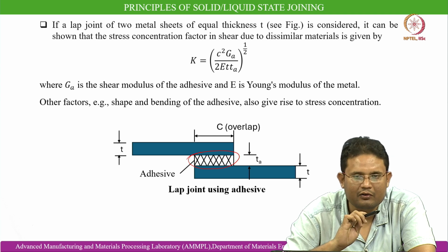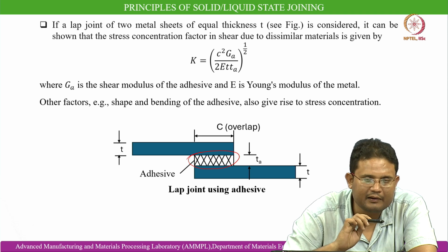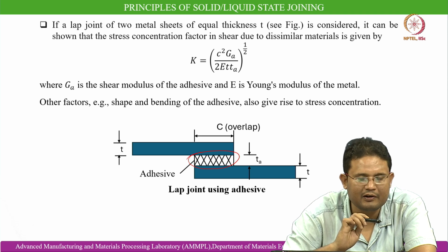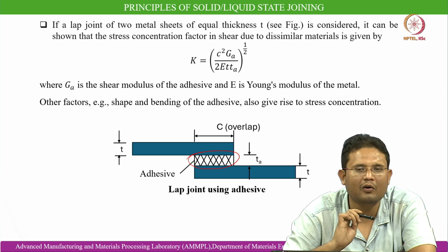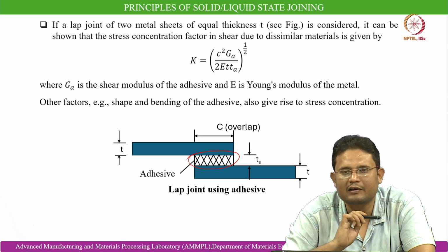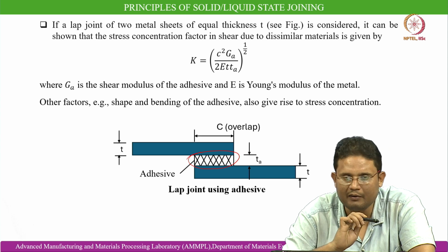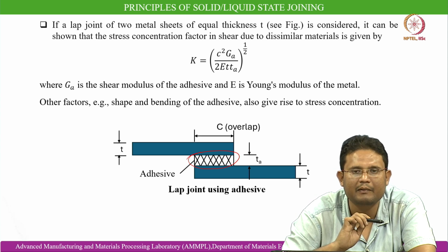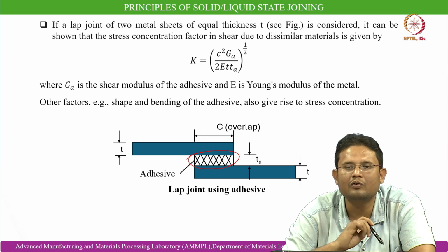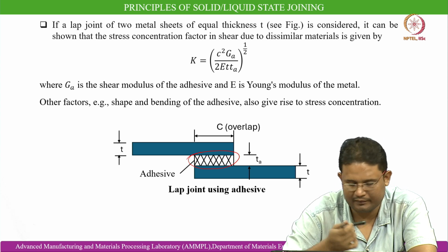As I told you earlier, an adhesive bonded joint is semi-permanent in nature, because the adjoining metal plates can be separated without causing any metallurgical changes, at the onset of an appropriate temperature and the mechanical force needed to overcome the strength of the adhesive layer.